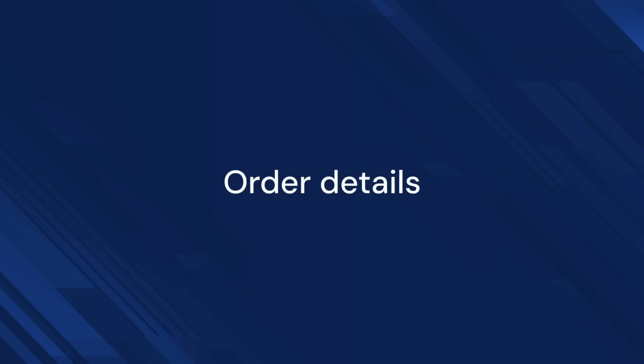So going back to this part, my initial thought is to place this part in a soft jaw, but there are more factors that we need to consider. First, let's consider the order details. Quantity. A short run will have different criteria than a production run, so we'll keep that in mind. Turnaround time. The turnaround time will dictate how we manage our time. It will also dictate how we manage risk.